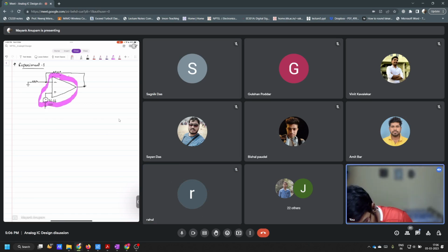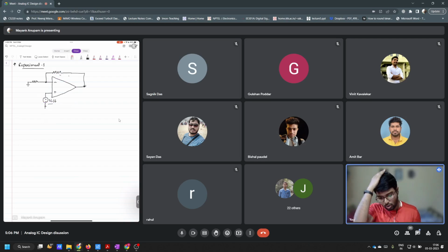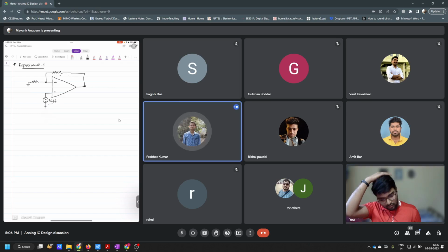So what is accessible to you is the terminal which is outside of this, isn't it? This is the terminal that is accessible to you. You can add anything here. So this was Vs, by the way. But now let me ask you, if you have to calculate V offset, if you have to find the effect of offset voltage, how will you do it? What does your intuition say? What does your common sense say? Short circuit the input. Correct.